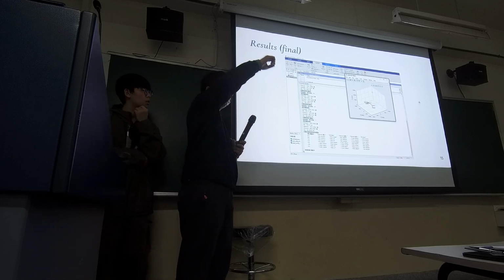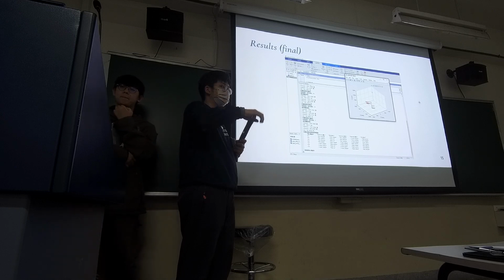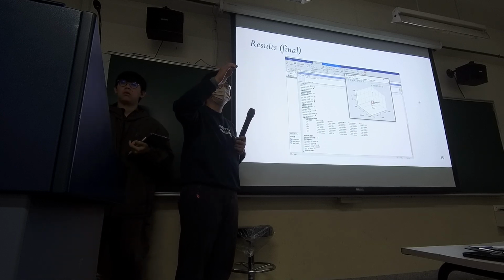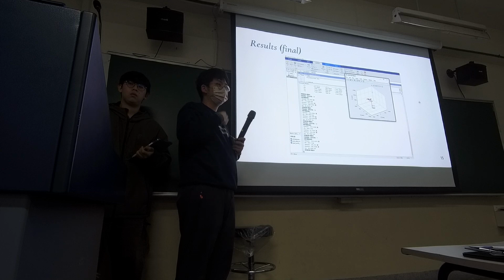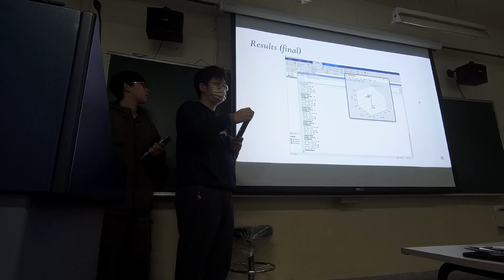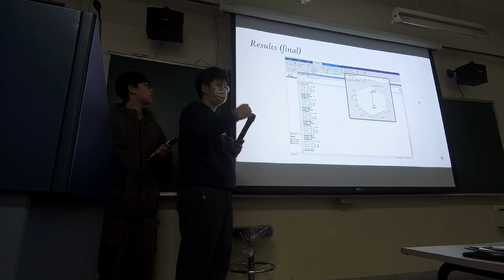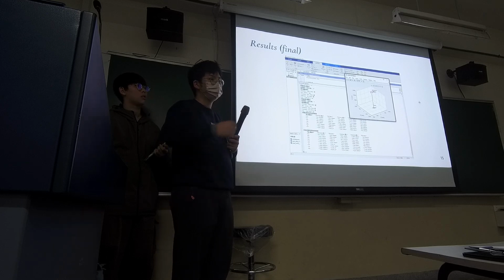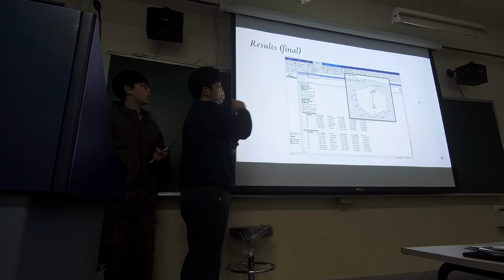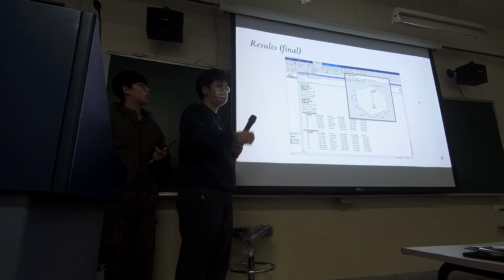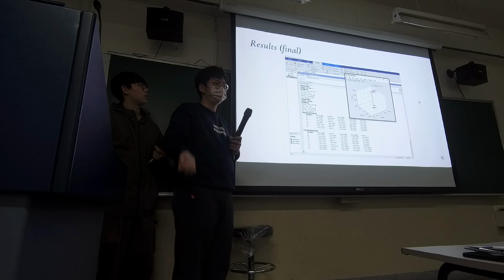We set the target point as x, y, z, and gamma, and we use CCD, and I give the origin parameters from joint 1 to joint 5, and I use the CCD to solve the new parameters from the origin parameters.